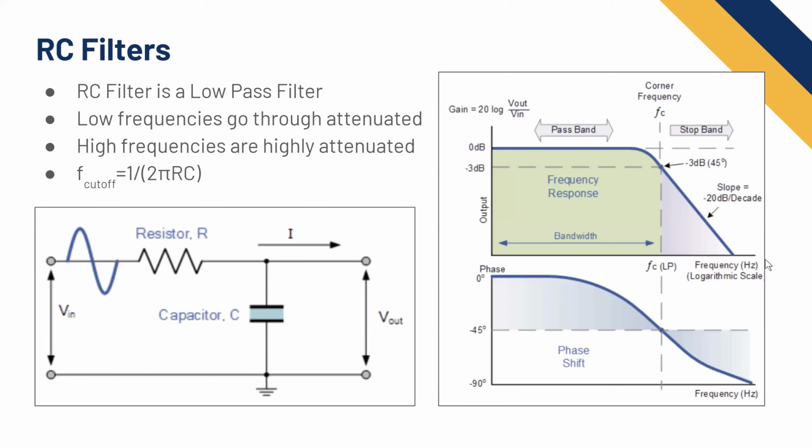All right, so now we know resistors and capacitors. What's one of the most interesting things we can do with that? Now we can make filters. Filters are very nice. If we make this circuit right here called an RC filter, this is what's called a low pass filter. It'll allow low frequency signals to go through, and all high frequency signals will not be able to go through.